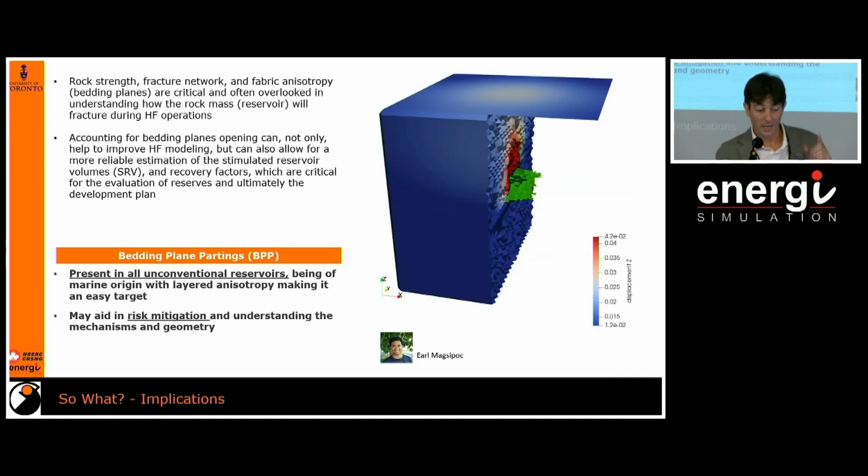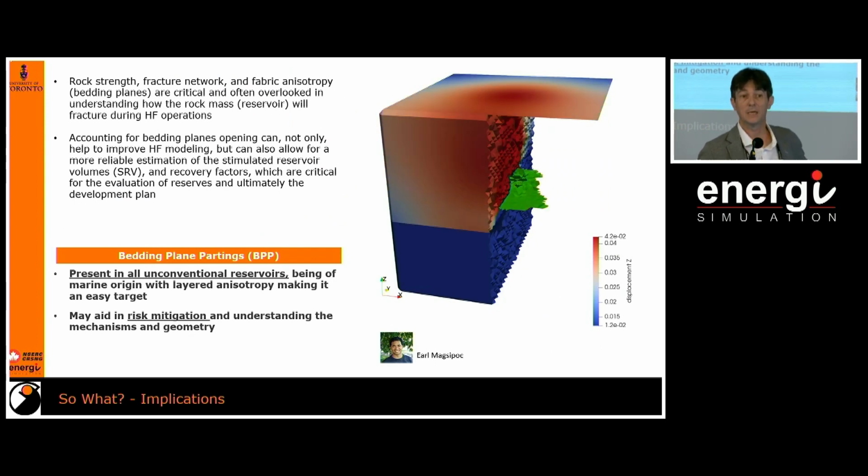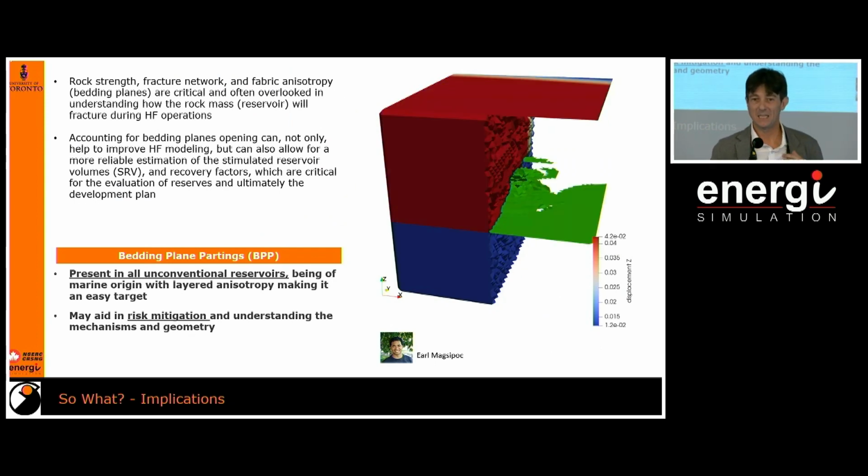Okay, thank you. If you look at the model, this is a 3D model that explicitly tries to reproduce the fracturing happening in the reservoir, especially the development and failure of this regional weak plane. You can see the fracture developing, and as soon as the fluid hits that particular plane, it extends in just a matter of a few instants.